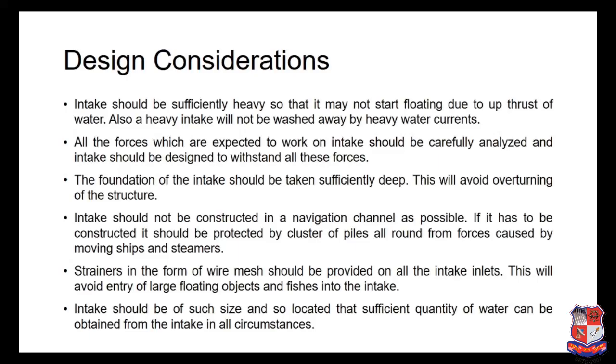The intake should not be constructed in a navigation channel, as far as possible. And if it has to be constructed in a navigation channel, then a cluster of piles should be provided all around the intake to protect it because of the forces caused by moving ships and steamers.